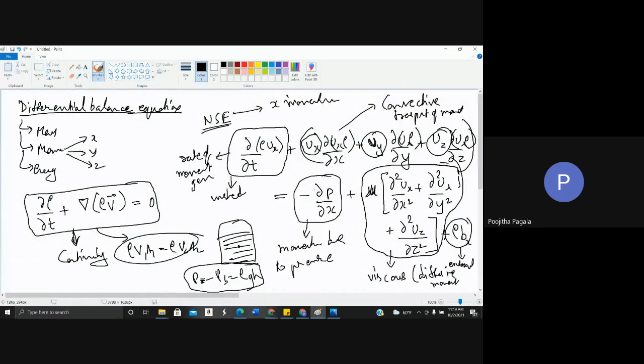So in the y direction, this becomes dou p by dou y, and this becomes rho by, and all these become uy. So uy is 0. Because uy is 0, ux is 0, and uz is 0, the fluid is stationary. This term will become 0. All these terms will become 0. Even all these terms will become 0. All you are left with right now is